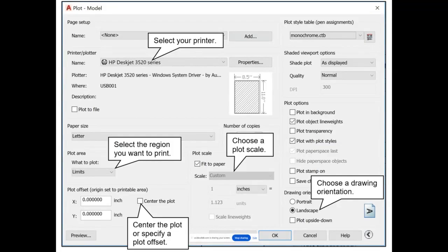And you go home and you open it up on your computer, which has a different printer. It'll give you a message saying, hey, this printer not found. And then it'll change the printer either to nothing or something else. And guess what happens? You go over to your layout, all your stuff gets moved.